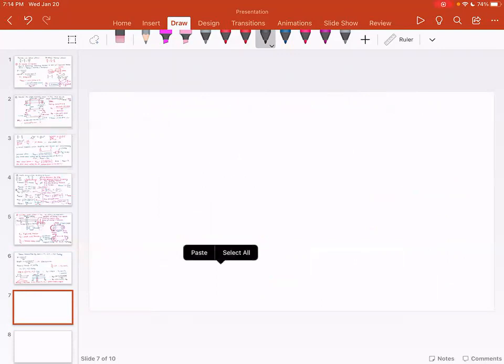My answer for the maximum bending moment, I will give you the value: Bm max is equal to 905.2 times 10 to the power 3 Newton millimeter. This is the maximum bending moment.